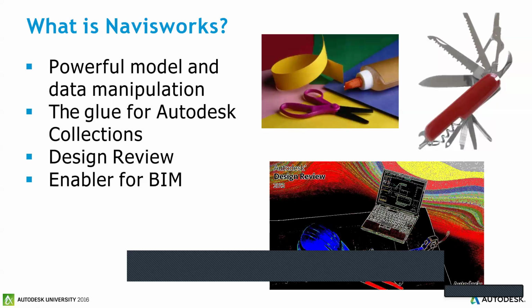This is where coordinate systems come into play. You should have common shared coordinate points so that one model can coincide and overlap with the other model at the same end. Then you can detect what all clashes are there within the model. You can generate clash reports out of it, and you will get an ID with respect to particular elements that are prevalent in the Revit modeling portions.